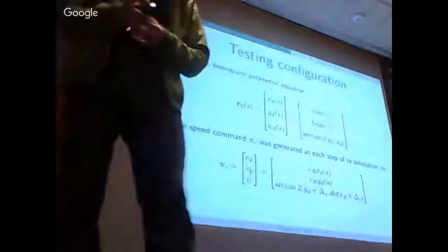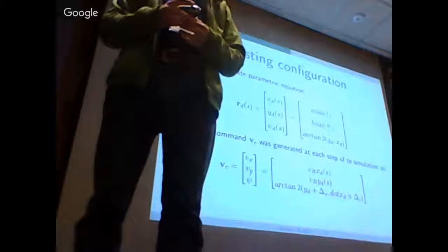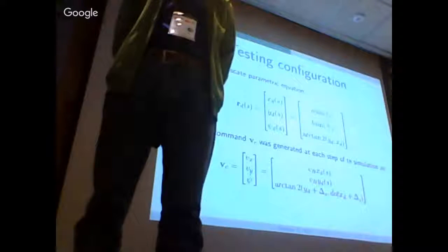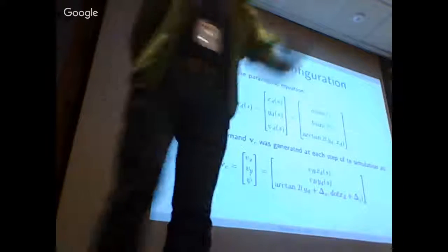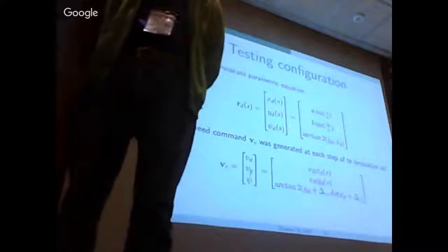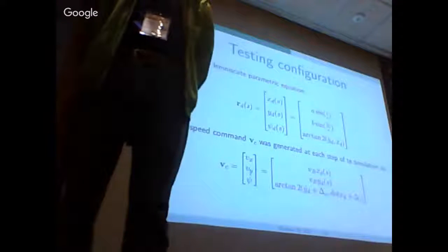What happens if you correlate these ideas with the biped robot? Okay. Legged robot. When it moves slowly, it's enough to consider the mass center location to be over the supporting area. That's static walking. When you move fast, then this static criterion is not good enough. Then Vukobratović showed that you have to consider the zero moment point. That's right.